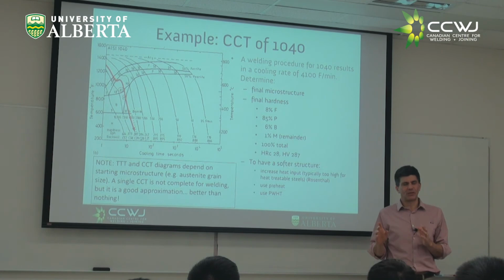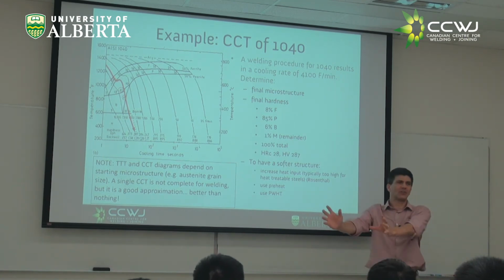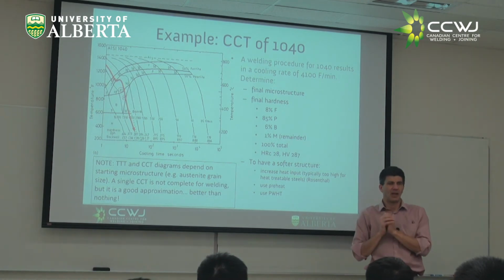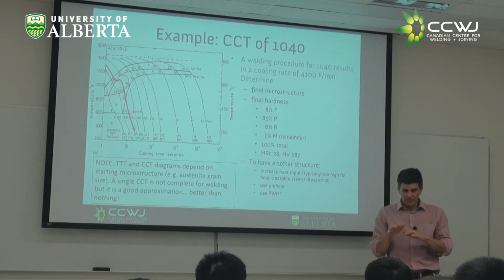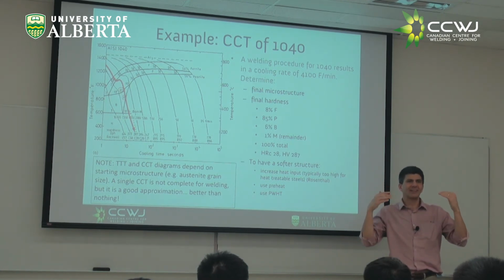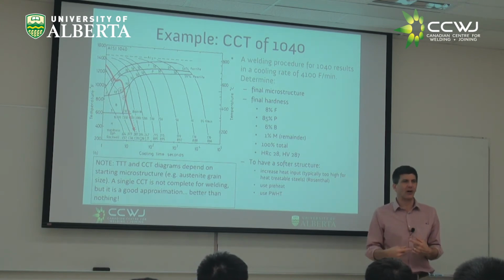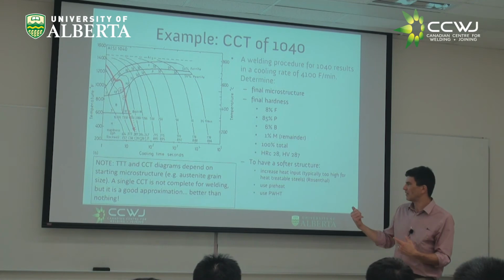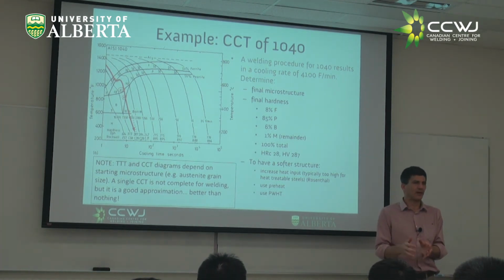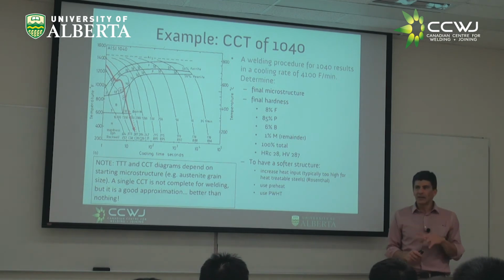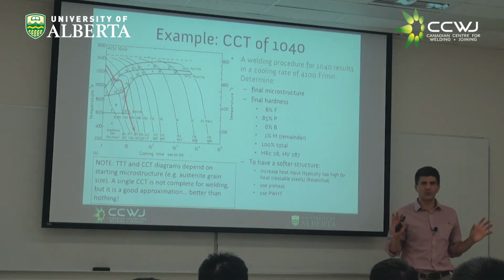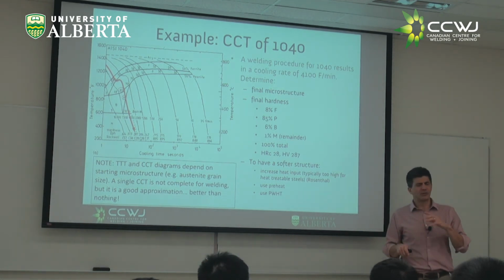If you need to do a post-weld heat treatment, you need to take your whole part to a heat treatment furnace. Very expensive. If you can use preheat, if it is a low preheat, you preheat it with a torch, like you were saying. If the preheat is too much, then it gets expensive again. And like everything in welding, there's no universal solution, because maybe you already had heating blankets in your shop, and doing a preheat is easy. Maybe you already have a heat treatment furnace and small parts, right? But what really matters is not that there is a universal solution, it's that there are many possible solutions, and you're aware of those, and you know why you would need them.